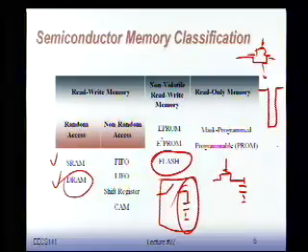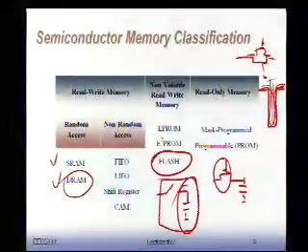I can make very nice trenches. You drill holes in the silicon, basically. And then you put some polysilicon in there, and some silicon dioxide, you go over it, and so on and so forth. And now my capacitance goes in depth. I really create a 3D structure, which gives me a lot of surface area for a capacitance, but at the same time, in the 2D space, on the chip level, it's very small. And if I put a transistor on top to access it, you're done. Everything is sitting on top of each other.